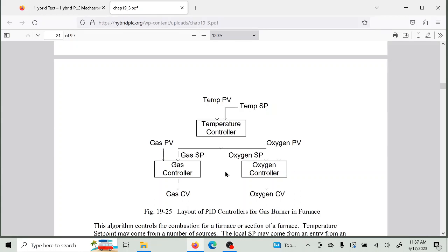Well, basically they were using them to turn on the gas and the air. In that case, they were using oxygen to control burners that controlled the heat in a glass furnace. So they were heating glass to 2200 degrees Fahrenheit, 2100 degrees Fahrenheit, somewhere in there, with PID controllers, just exactly the way that we described them above.